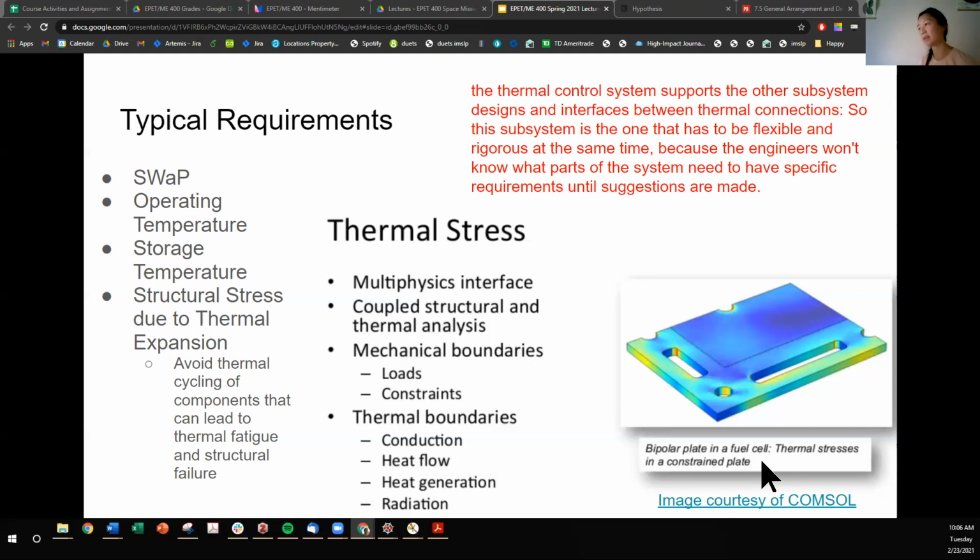I mean, there are things you can control for beforehand, like generally you know what the orbit is and what the space environment is. You know whether the spacecraft is going to run. If it's interplanetary, it's most likely going to be cold. But yeah, there is a little bit of waiting to understand the power dissipation of the components inside and their individual temperature ranges.